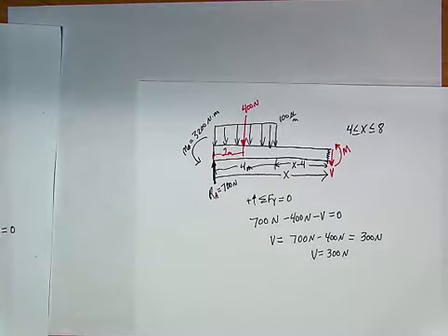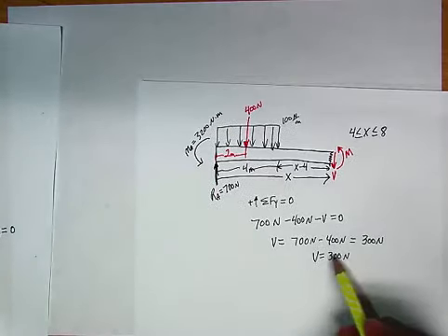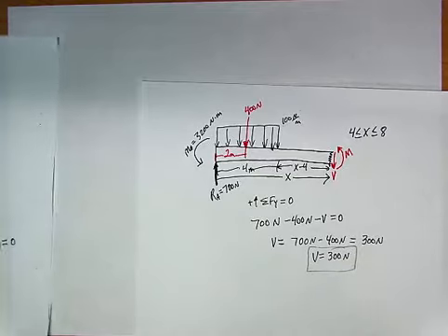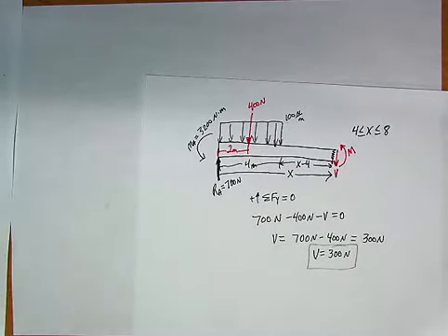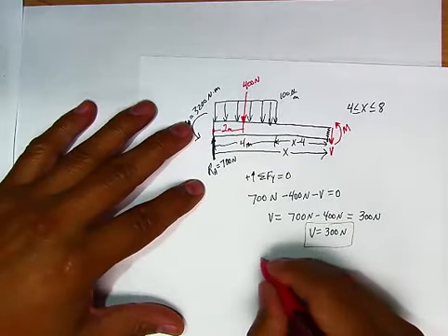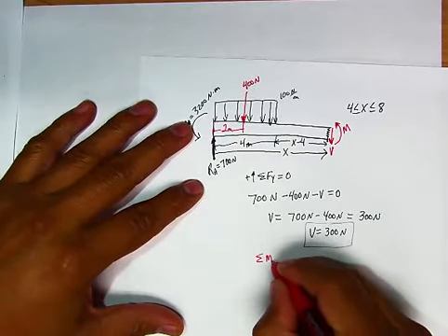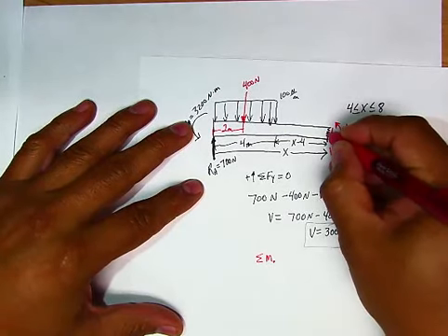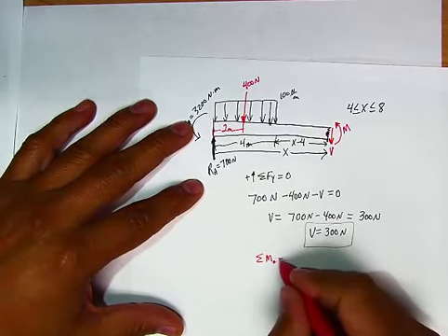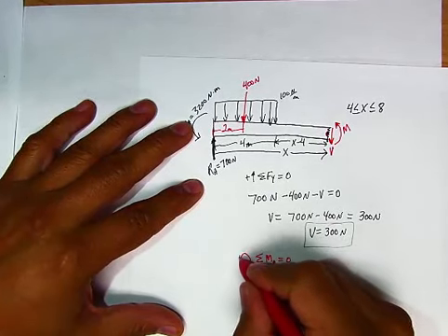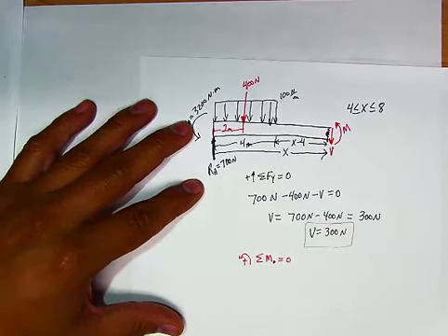All right. We're going to also box this one up just like we did the other two. And let's go ahead and also solve for our moment equation. That is done by doing the sum of the moments about this point right here. They must be equal to 0. Counterclockwise is considered positive.